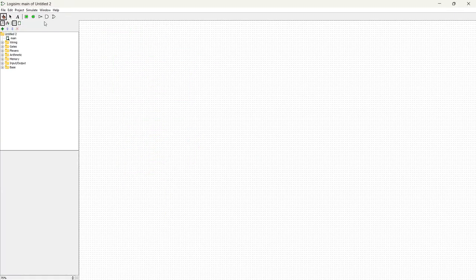If you need 2, then customize that one to 2. When you get a gate through the Logisim software, it will automatically come as 5 inputs. So if you don't need 5 inputs, please customize that through edit properties. You can see that, right?